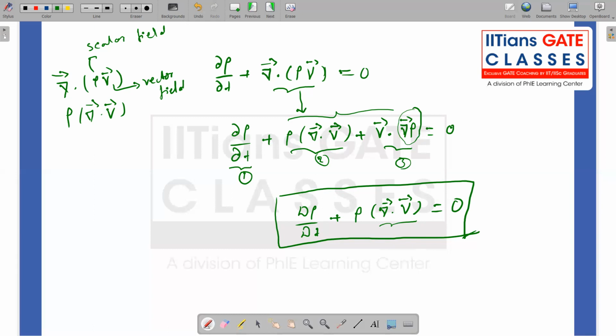We can use the divergence. All we have to satisfy is that the velocity vector is divergence free, or I can write the velocity vector as a gradient of some potential. If I can write that, I can use the potential equations even for a compressible flow.